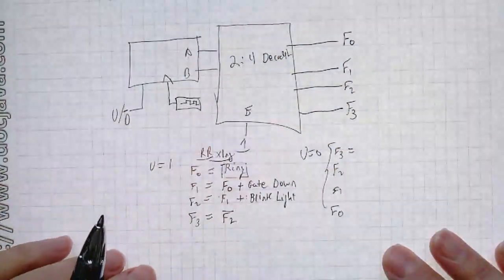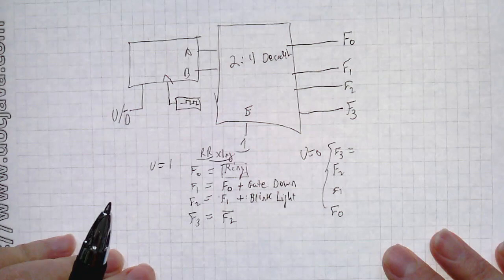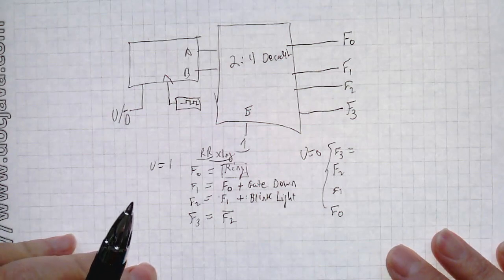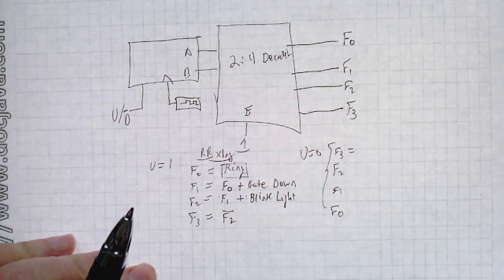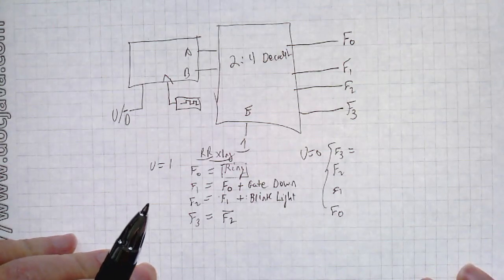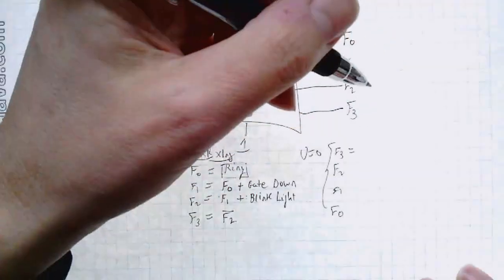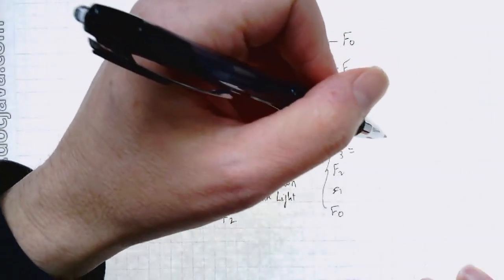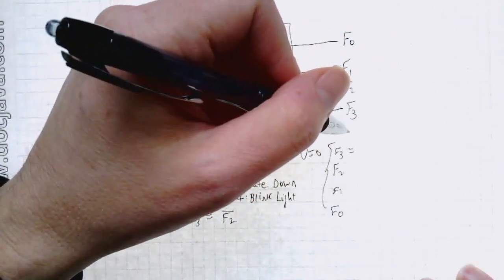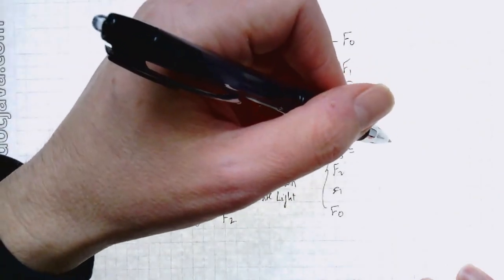Saturn V booster rocket has 6.2 million pounds of propellant, which is used to create 680 metric tons of thrust per F1 engine, and there are 5 of them, giving a grand total of 7.5 million pounds of thrust. That is 3 tons per second of propellant. That's a lot of propellant, and that's liquid oxygen and kerosene, rocket grade kerosene, of course.